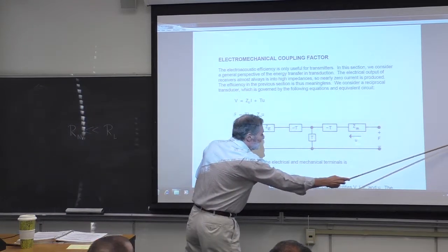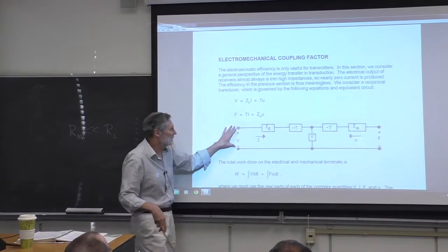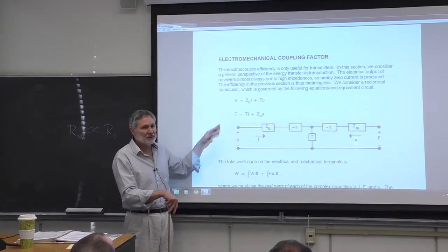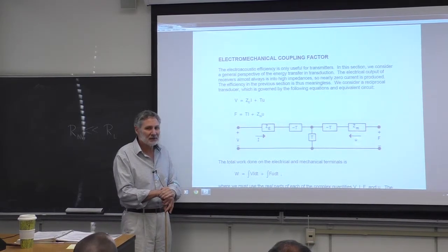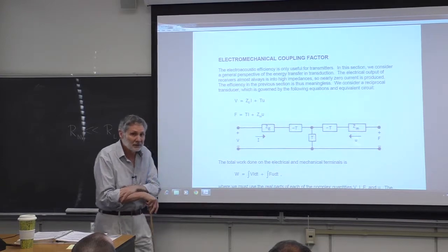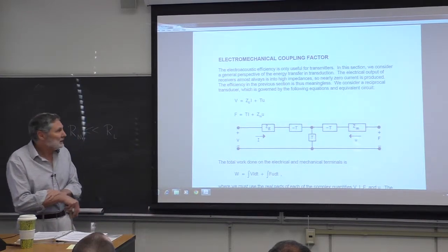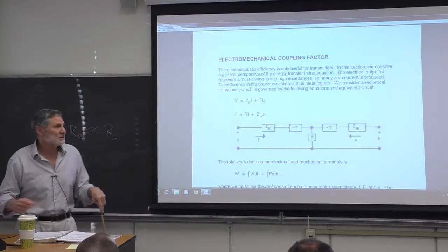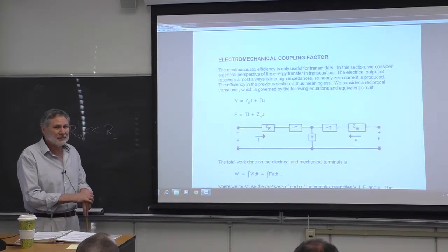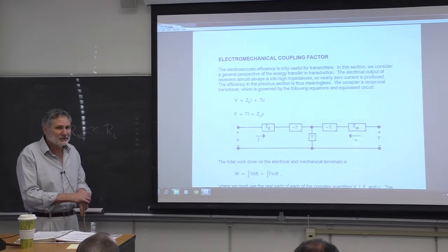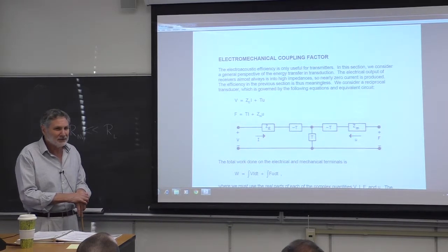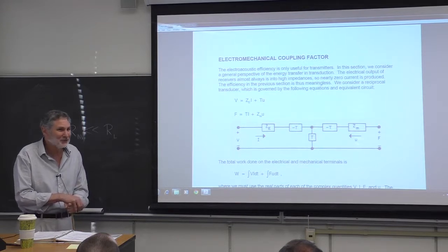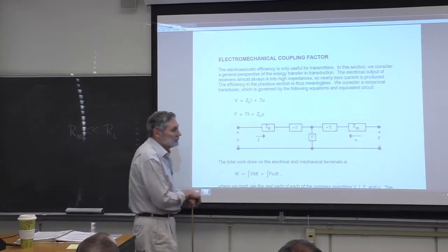So in the sensor case, we have an acoustic wave coming in here. We're picking it up here. Almost always this is being put into some high impedance analyzer. So there's very little current, right? So the efficiency from this previous section that we just talked about is really kind of meaningless here. It's going to be close to 100% and it's really not telling you anything. Okay, it's really not giving you any useful information. So we need to look at this differently.